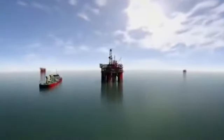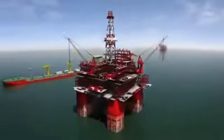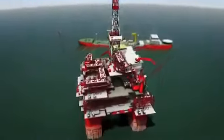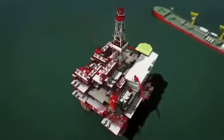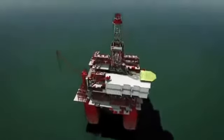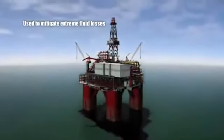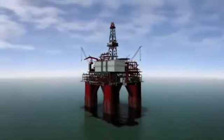Pressurized mudcap drilling is one of the 4 variations of managed pressure drilling, or MPD, recognized by the International Association of Drilling Contractors. Pressurized mudcap drilling is used to mitigate extreme fluid losses commonly found in highly depleted and naturally fractured formations.